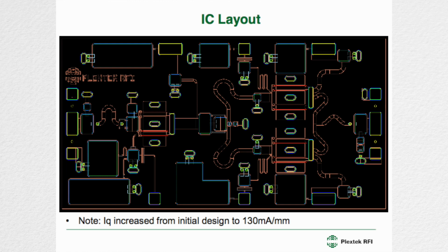And this is what we ultimately came up with. There's an RF input here, ground signal ground, RF output here, ground signal ground, and 2 transistors in the output. This is the shunt inductor that gives us the shunt 0.3 nanohenries, and in this instance is essentially tuning out the output capacitance of this transistor. Then we have some low pass matching. You can see here we've got 2 shunt capacitors going down to ground.